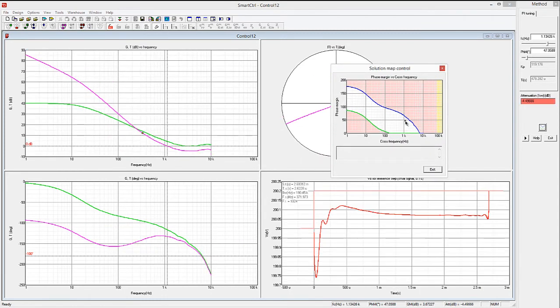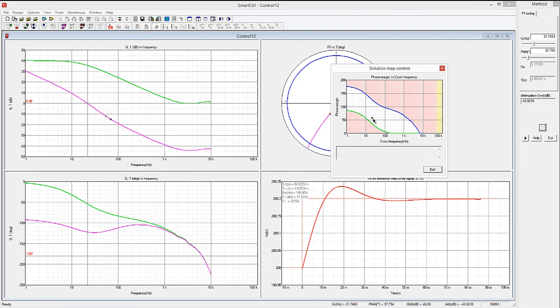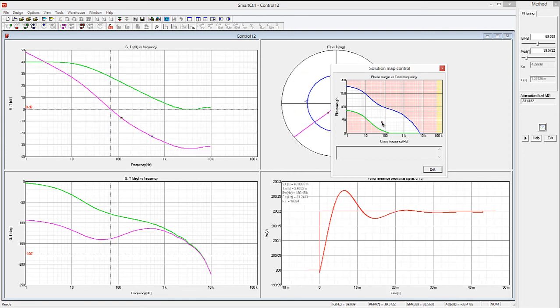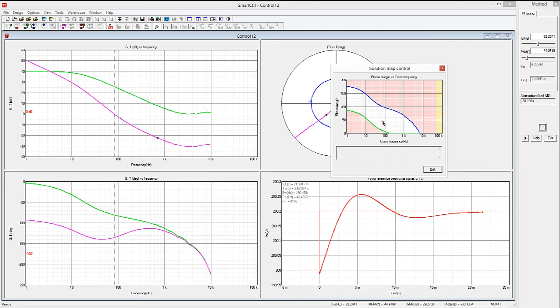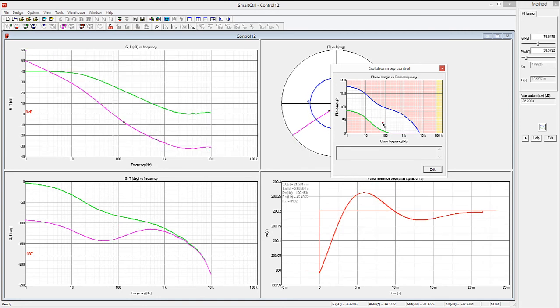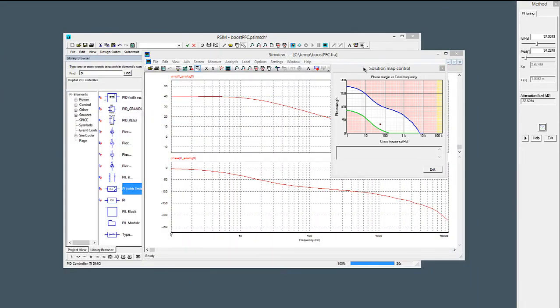And now, again, back to our same issue. We can try to do something really fast, but it's not going to work because we're not attenuating that 120. So we need to come back into one of these regions to attenuate that 120. Maybe we can push it a little bit out over here. Again, a lot of phase margin, we're not getting a lot of attenuation. If we can really just drop the phase margin down, we get some good attenuation there. So something like this, cross frequency of 57, phase margin 34, and let's roll with these numbers.